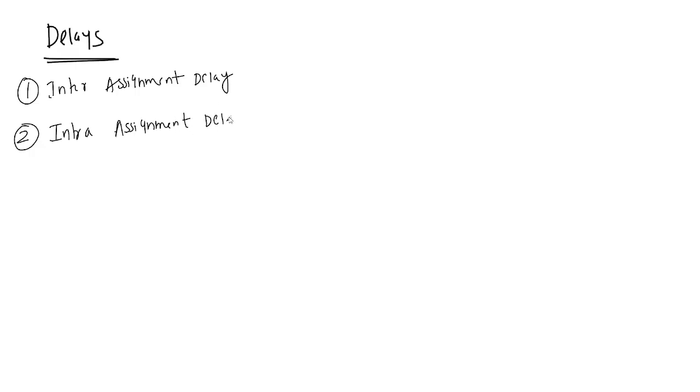So what are inter assignment delay and intra assignment delay? In detail we will discuss. Inter assignment delay is whatever delay we mention on the LHS. For example, if you take #5 a = 1, this is inter assignment delay.